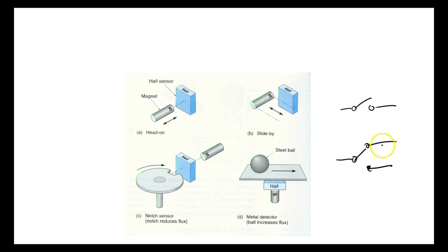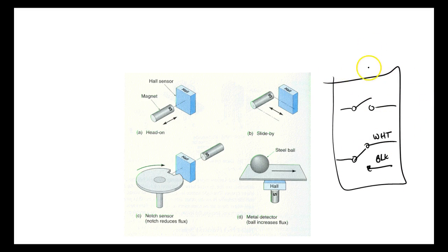And one of them, the normally open, I think is black. And then they'll add a 4th wire, and it'll be white. So a 4-wire sensor would have 4 wires coming out. And then power would be what? The power of the sensor, we would have what? Brown. This is DC, by the way. This would be plus.